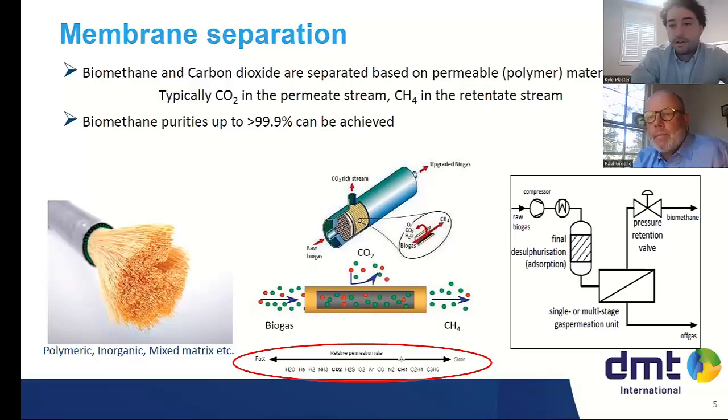Along with that, again, we already talked about this, but all pollutants have to be out, particulates have to be out, and then the correct pressure and temperature. What kind of compressor do you typically lean on for this service? Usually screw type, and we'll usually have a VFD, sometimes just a slide valve if it's not necessary for the project. So that turn down that you mentioned of getting down to 20%, that's really about the VFD control? That's exactly correct. Yeah, because the membranes can handle low flows. Our system can actually close certain membranes so we can have the same amount of flow to the membranes no matter what's coming into our system.